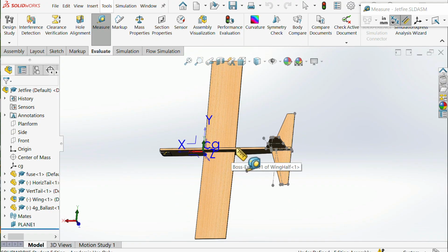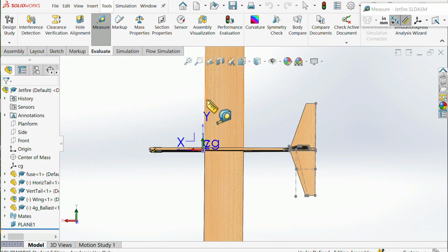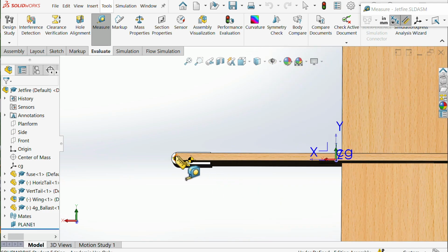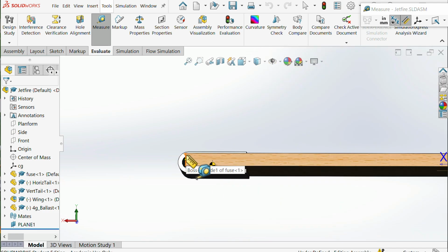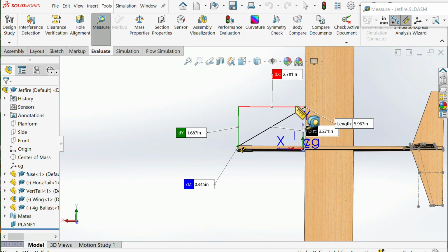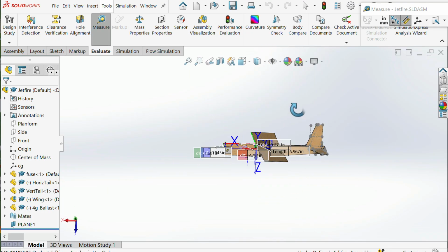Now, if you have a tapered wing, you're going to need to calculate the mean aerodynamic chord, and then you just draw that on here on the wing, just like I did it on the tail, and then you can just calculate. There's the leading edge, and there's the leading edge there, and that's basically 2.8 inches back, in my case, for this rectangular wing. Your wing may be different if you put a taper in it.